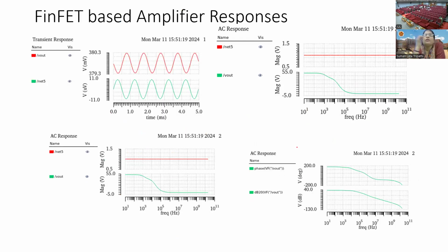For that, we have seen the responses that even if the voltage is in microvolts, you can amplify it into millivolts. So it is capable of amplifying voltages in microvolts to millivolts. If the voltage level is very low, like biopotential for biosensors, where you are trying to measure the biomolecule charge in terms of voltage, that voltage will be very small.